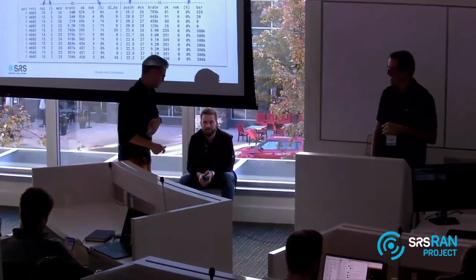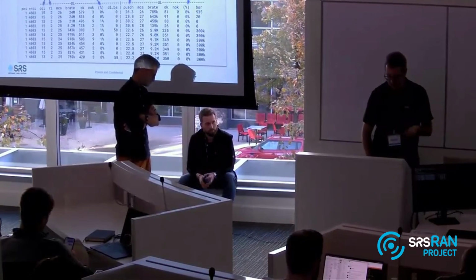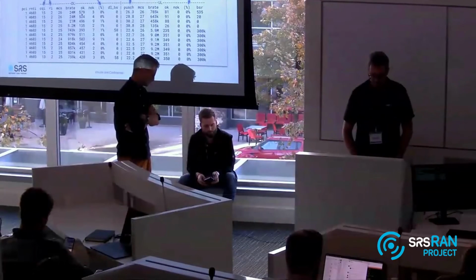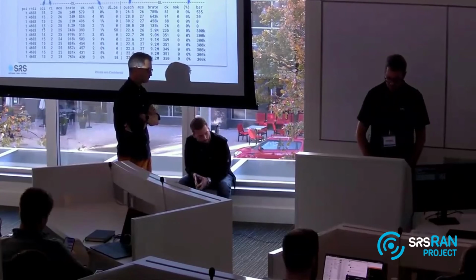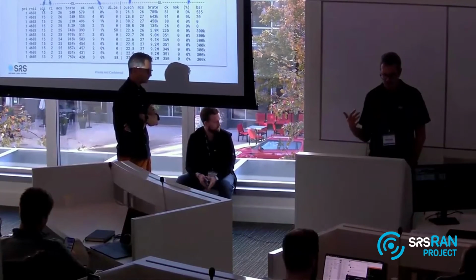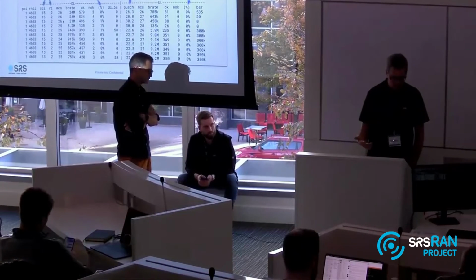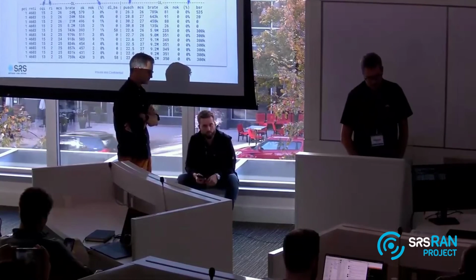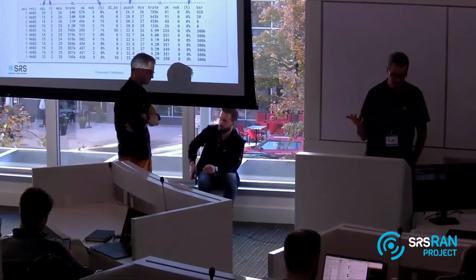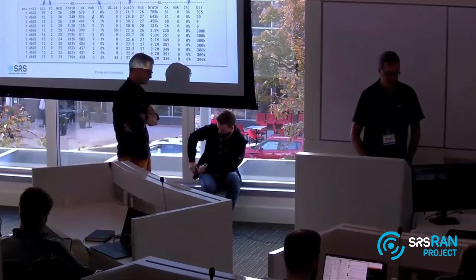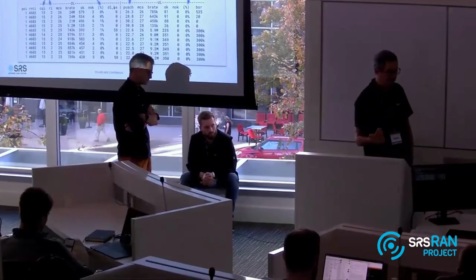So it's not critical. When you start running the gNB, this is the console that you see. All of you are probably familiar with it. I will just go through the different parameters. We have here the CQI that is reported by the UE, the rank indicator. This is the MCS that we are using for the downlink, the bit rate, the number of positive ACKs, and the number of negative ACKs. This is the DL buffer state.